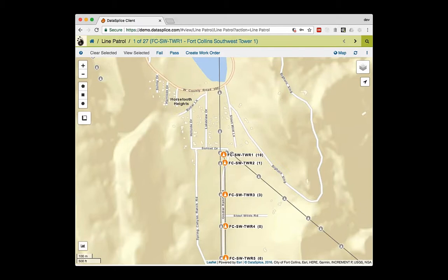So in your Maximo system, you may have work orders that are incident upon an asset, and an asset may have an asset ID. And likewise, in the GIS system, you may have these towers, as you're looking at on this screen here. These are electrical towers with electrical cables between. Each tower may have an MX asset num, for example. And we'll know that the value for the tower's MX asset num is the same as the value for the work order's asset ID. And in that way, we can know that these gray towers don't have work orders on them, and these orange ones do.